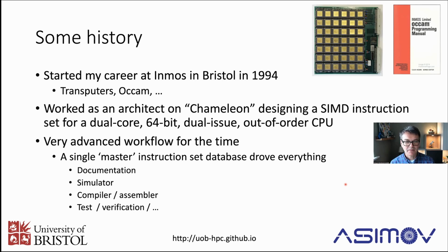But the most impressive thing about what this team was doing, and you'll understand why this is relevant to the talk later on, is the team had put together this amazing, very sophisticated workflow where there was a structured specification for the instruction set. This was before XML or YAML or any of these things, but it was a sort of structured text file format. You specified the instruction set in this one file, and anything you changed in there automatically rippled out across the entire workflow for the whole processor design. Even the documentation, all of the instruction set manuals, were built off of this file.